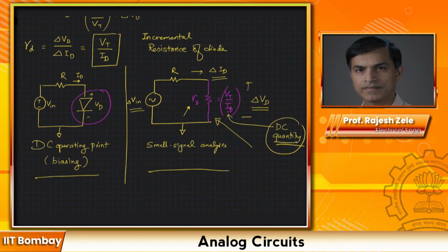It may not take long for a small circuit, but if you're trying to simulate a whole chip or a really large circuit, then it will. So that's the reason we like to do AC analysis or small signal analysis even in simulations, so that we get a quick answer and a quick insight into how the circuit is going to behave.